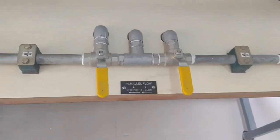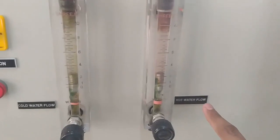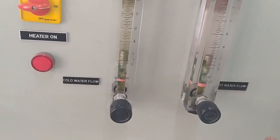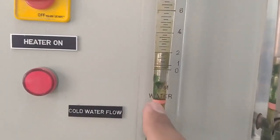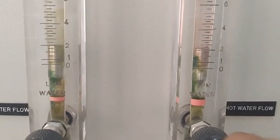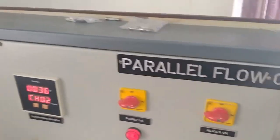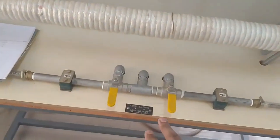While conducting the parallel flow experiment, here you can see the water flow rate for the cold water and the water flow rate for the hot water. The rotameter is there to measure the flow rate. First you have to set the water flow rate in both rotameters the same. Here I set the cold water flow as 2 liters per minute, 2 LPM, and the same for the hot water. Leave it for some time so that the experiment comes to steady state condition. After that we will conduct the experiment, first on the parallel flow heat exchanger.